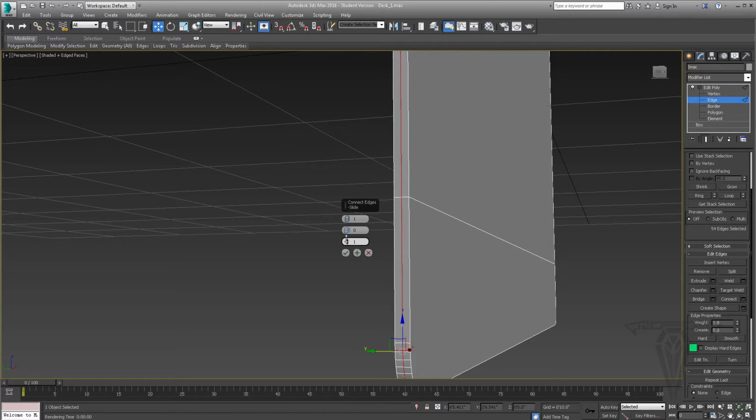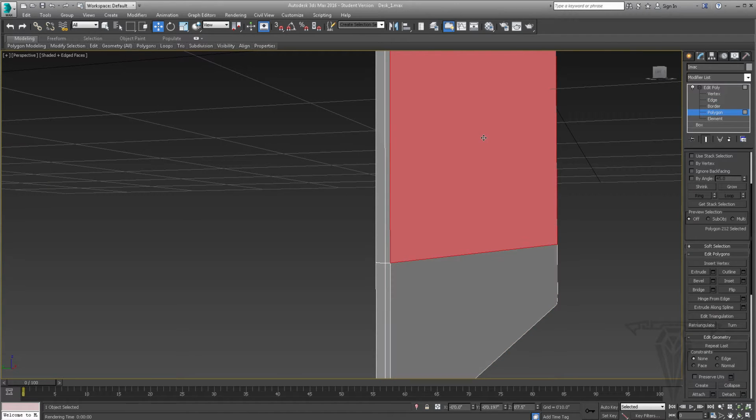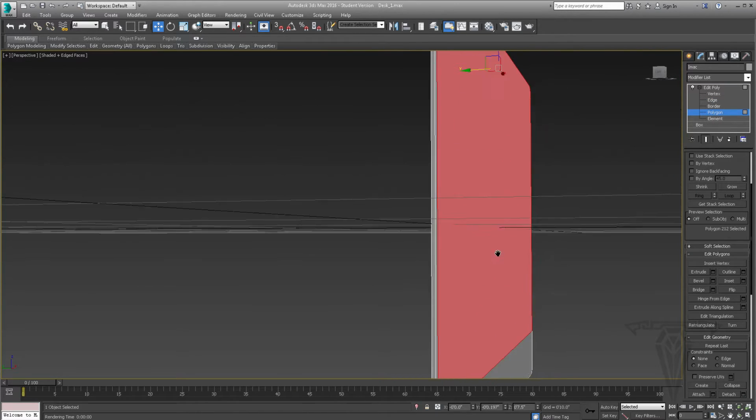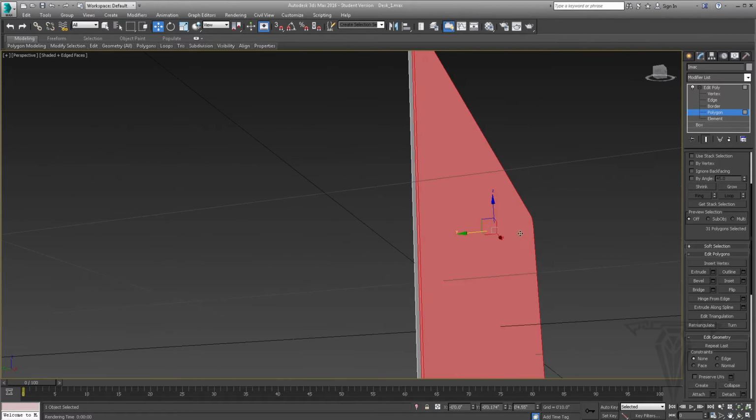I'm going to slide the connection over. Probably to about there. So 34 looks good. Let's go 30. Yeah, check mark. Okay. Now I'm going to go to Polygon, select this front polygon right here, and say grow. Okay, so it grew top area.